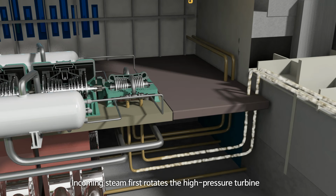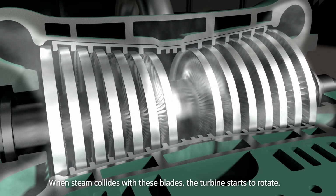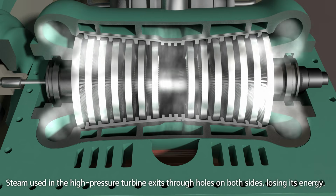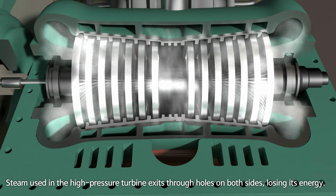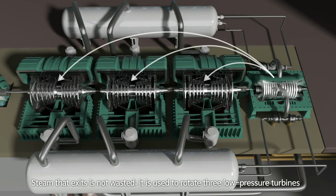Incoming steam first rotates the high-pressure turbine. Inside the turbine, there are many blades. When steam collides with these blades, the turbine starts to rotate. Steam used in the high-pressure turbine exits through holes on both sides, losing its energy. Steam that exits is not wasted. It is used to rotate 3 low-pressure turbines.